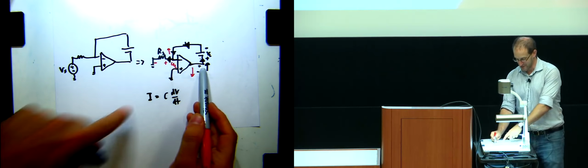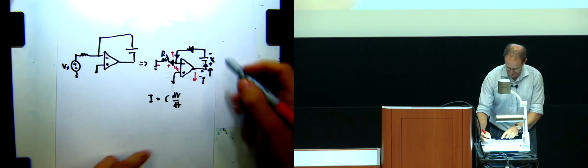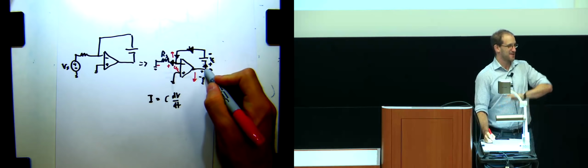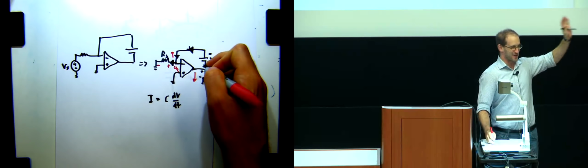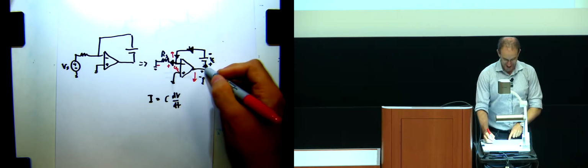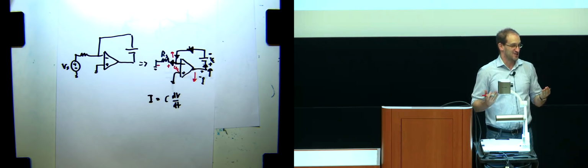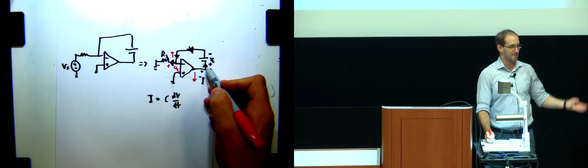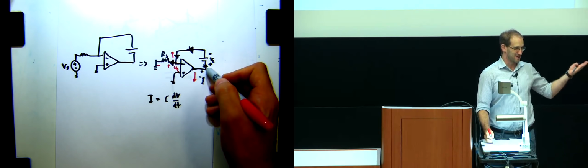Oh, you mean in this case where I'm checking for negative feedback? Yes, sure. So the question was, why is it that U2 goes up? Well, remember, the procedure we use is we say arbitrarily, through some magic fairy that came from the outside world, I take the output of the op amp and I cause it to change. In this case, I decided that I'm going to change the output of the op amp to be moving up, meaning the voltage is increasing relative to ground.